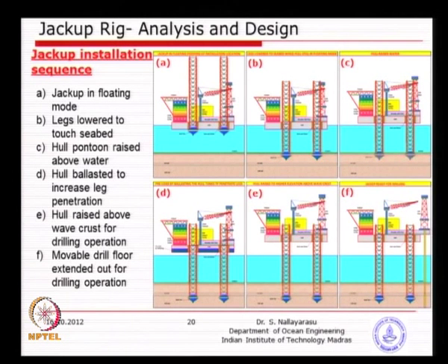Hull pontoon raised above water. So, basically in that condition, some amount of reaction or some amount of bearing has been achieved, so the hull can be tried to move. As it moves, the leg also will penetrate, because as the hull is going upwards, what happens? It is coming out of water, it becomes heavier, and if it becomes heavier, the legs will penetrate. This is the situation where it is slightly dangerous, because instability will occur, because at the same time the legs are penetrating and the hull is trying to come out.